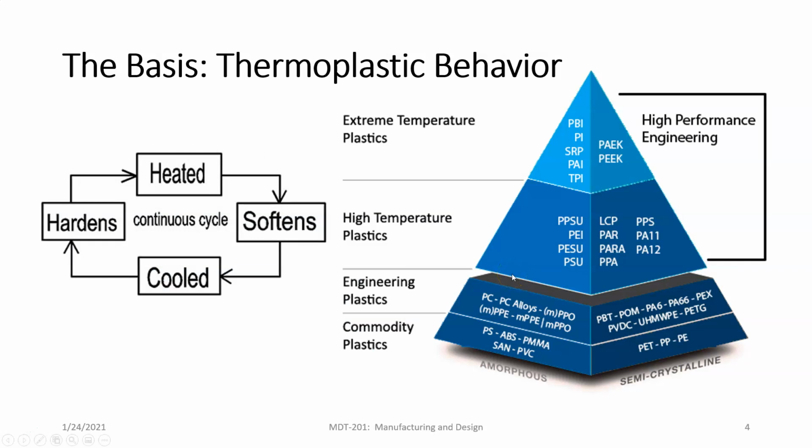Okay. So now, looking at thermoplastics, focusing in on thermoplastics. Okay. Remember, we have this continuous cycle. So that differentiates thermoplastics from thermosets. That you can heat them, they soften, they cool down, and they harden, and then you can repeat that cycle. All right. Thermosets, you can't.